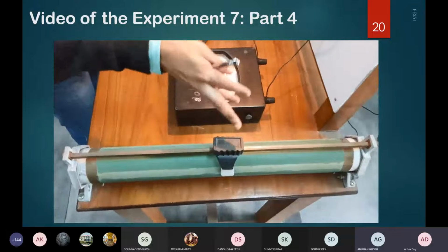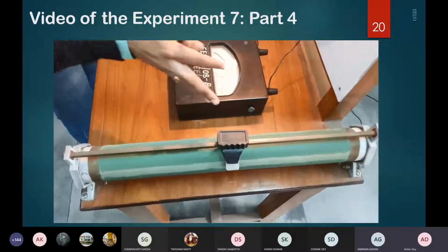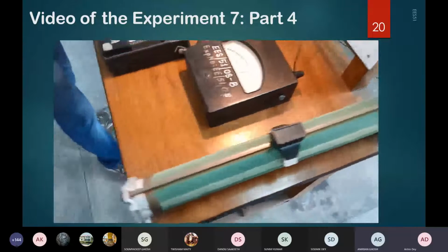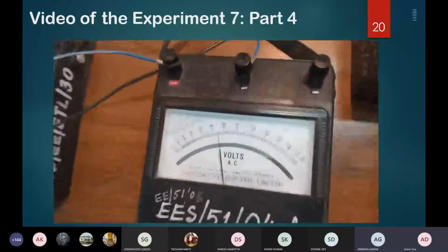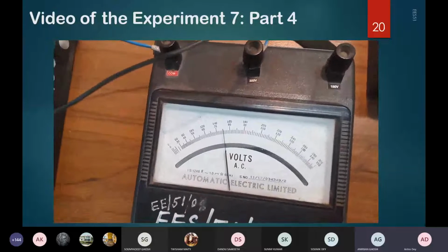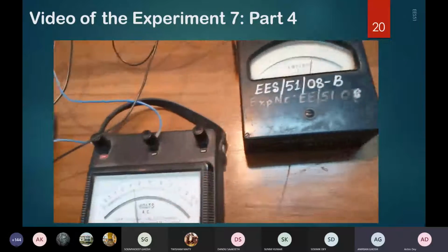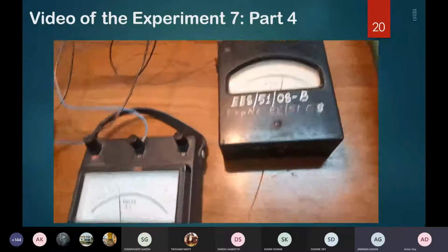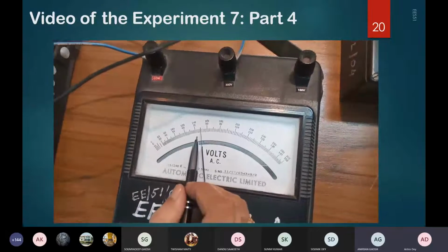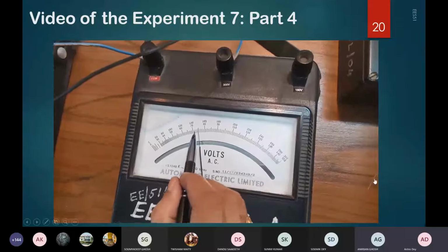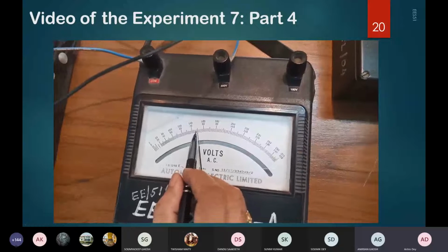So when we keep it at the 50% position, we get approximately 100 ohm here. Okay, so we'll verify that by recording the drop across the lamps. If you note the reading V2, this reading is basically 230 minus the drop across the external resistance, which is what is applicable over the two lamps connected in parallel. So we can see it is supposed to be 155. Okay, so we have taken this reading, which is 155, and as per the table it will be V10.